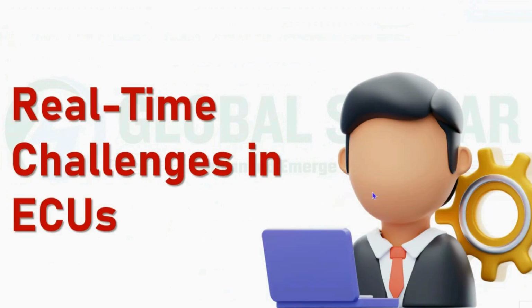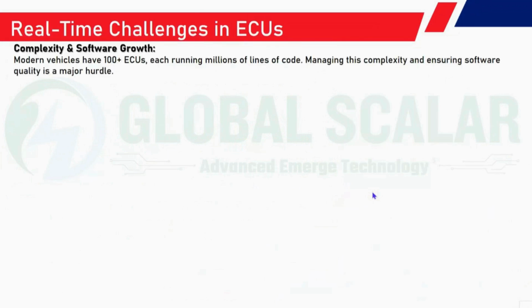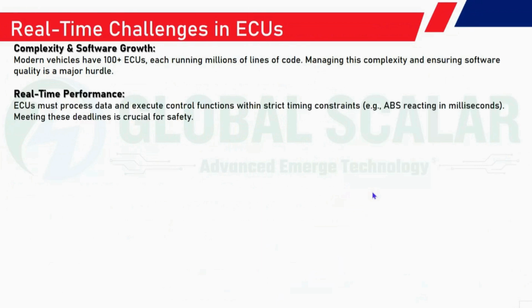And what are the real-time challenges in the ECUs? The real-time challenges will be the complexity and the software growth, because modern vehicles have 100 plus ECUs, each running millions of lines of code, and managing the complexity. We need to ensure that software quality is a major hurdle. And real-time processing, the ECU must process the data and execute the control functions within strict timing constraints. For ABS braking or the airbags, it is time critical. And meeting the critical safety features will be one more challenge.